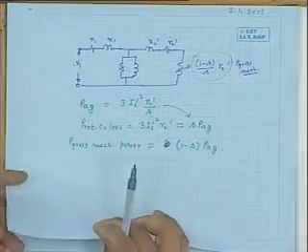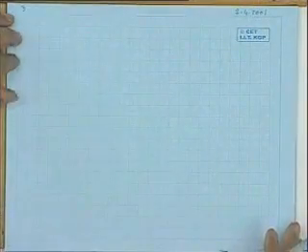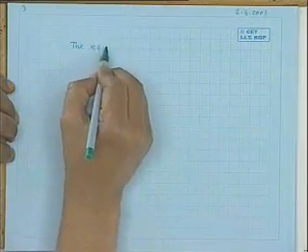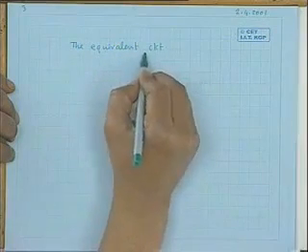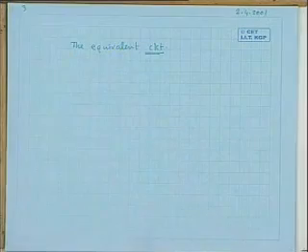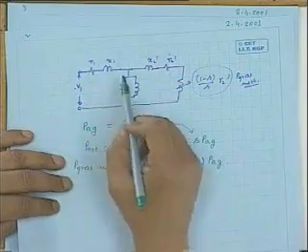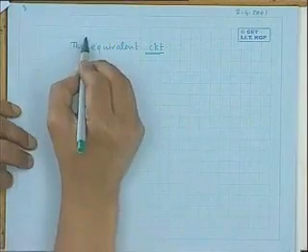Now today what I will do is this, we shall try to find out the nature of the torque slip characteristics of the induction motor by simplifying this equivalent circuit a bit to begin with. What we will do is draw the approximate equivalent circuit like a transformer. You bring this parallel branch in front of the supply, because these are small compared to this parallel branch impedance. So this is approximate.